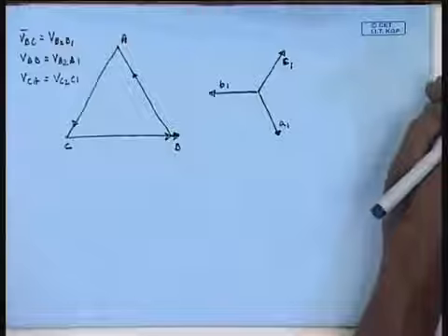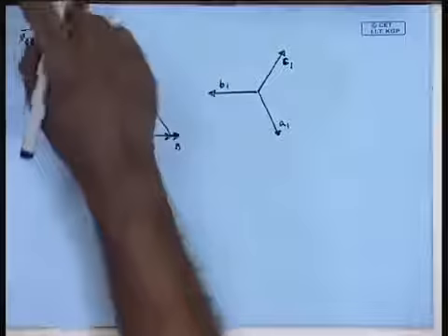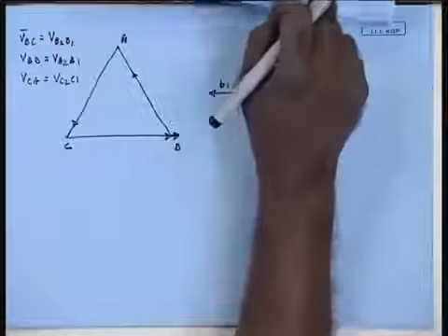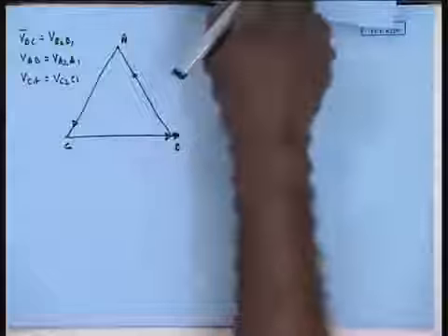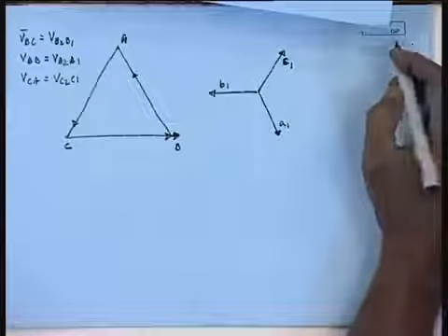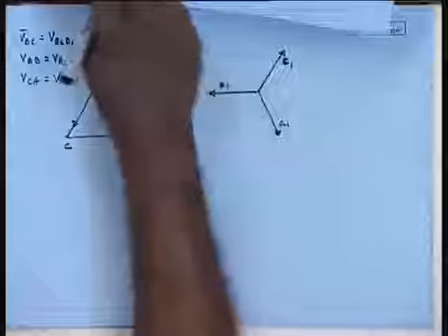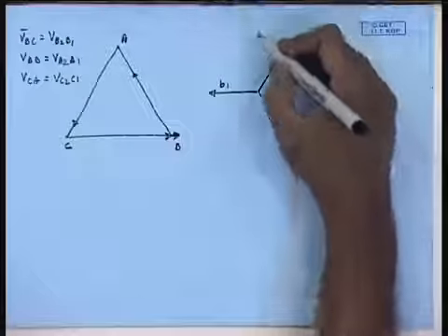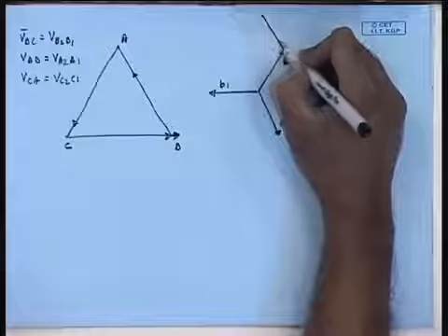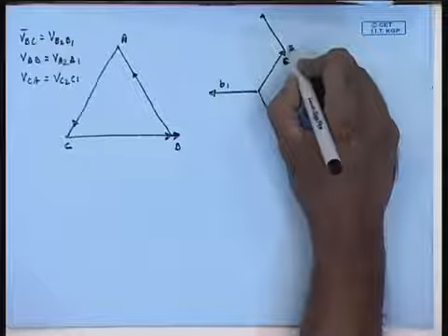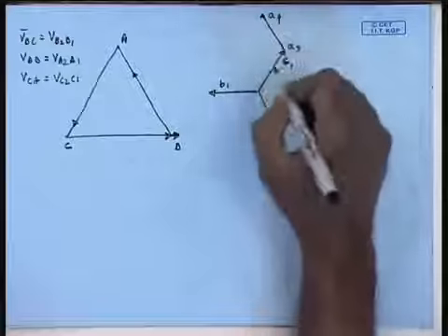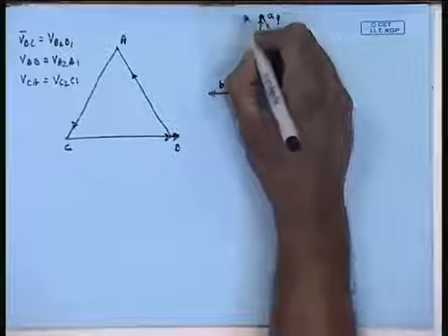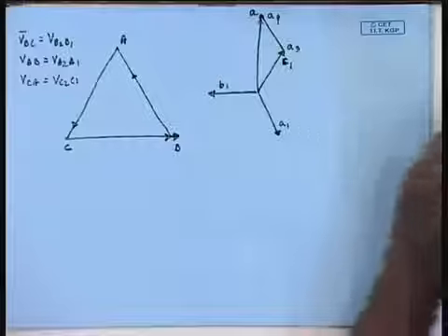Now, the phase A is obtained by adding the phasor VA4A3 with that of A3, which is connected to C1. So, phase A is obtained by adding phasor A4A3, which is parallel to VAB A2A1, with this phasor. So, this is A3 A4 and this is the voltage VA, this is the terminal A.